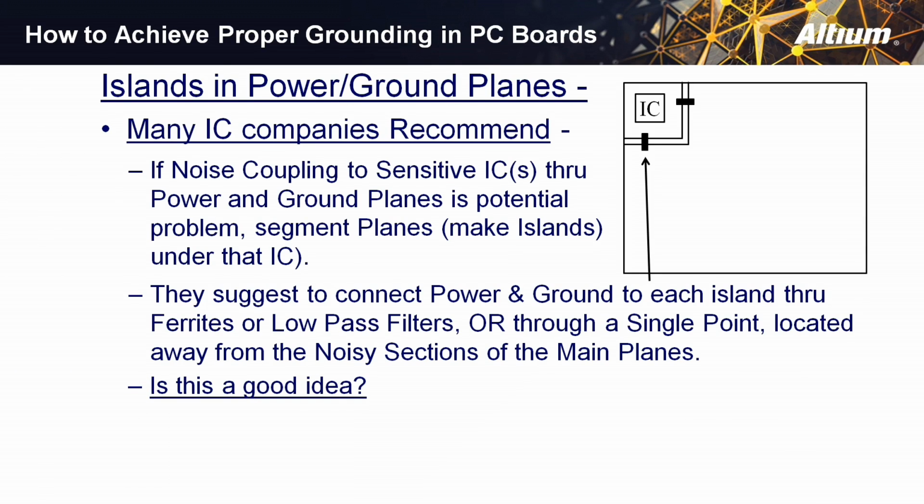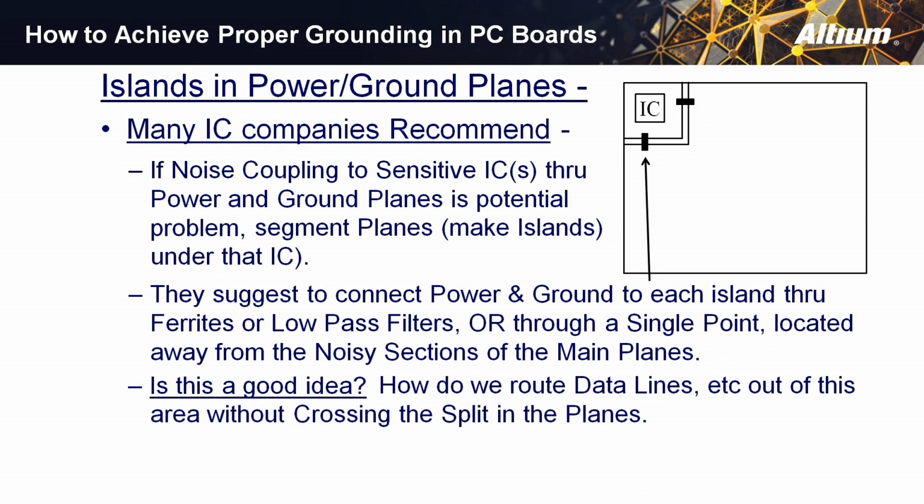Is this a good idea? Well, if you didn't care about signals getting in and out, and you could make the area of power and ground under the sensitive IC large enough, then yeah, it's probably not the worst idea in the world. But what about the reality of getting signals in and out of the board? How are you going to route data and address from that isolated IC into the other area of the board without crossing a split plane, which we've already discussed is a terrible idea? Well, the answer is you can't.